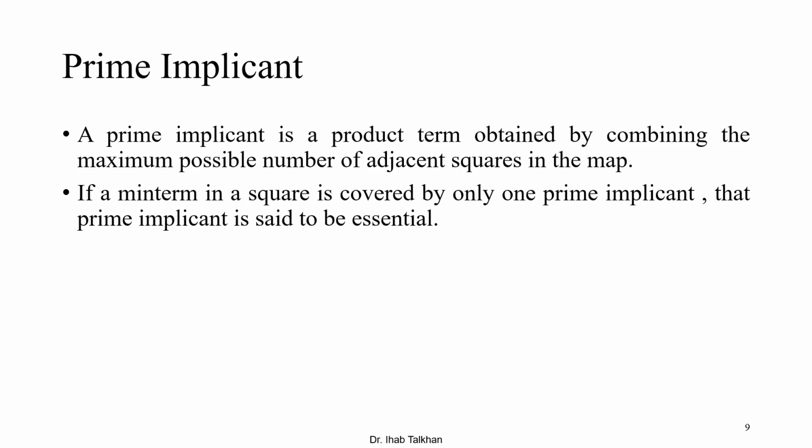A prime implicant might be essential or not essential. Essential means that you have to take it, there's no other choice. But non-essential, you might have a choice of either two alternative solutions, or you might exclude it from your equation. So you're going to see from the next examples what's meant by essential prime implicant and non-essential prime implicant.